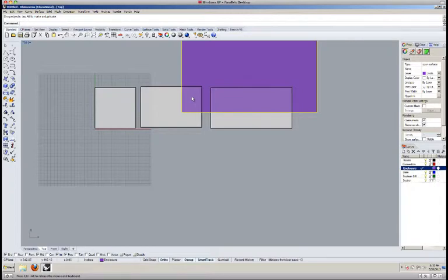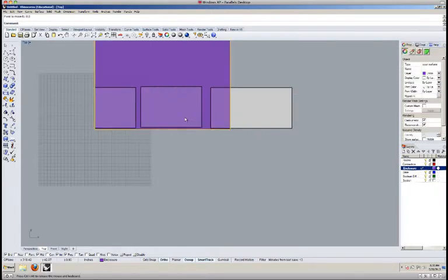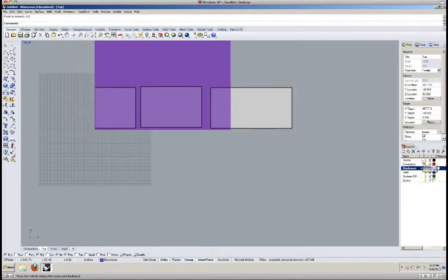So I'm going to move this enclosure box to have its bottom left corner point be at 0, 0. So move, type in M and hit enter. I'm going to click on the bottom corner point, so it's asking me what I want to move. So I want to move this point to the 0, 0 point, and it will snap it over there. And then I can lock this layer, and I'm going to activate the rooms layer. So I'm going to lock this enclosure layer for now so that I don't accidentally move it around.